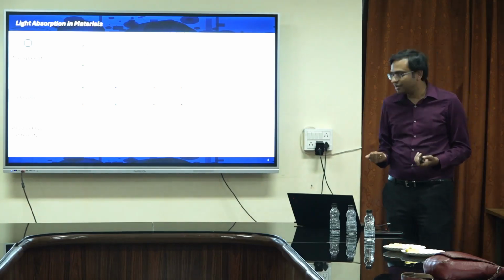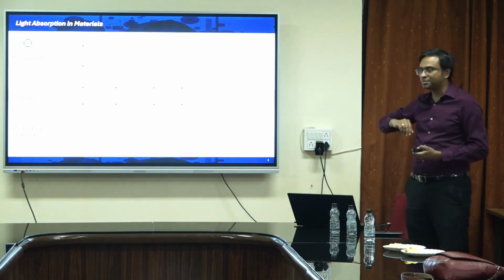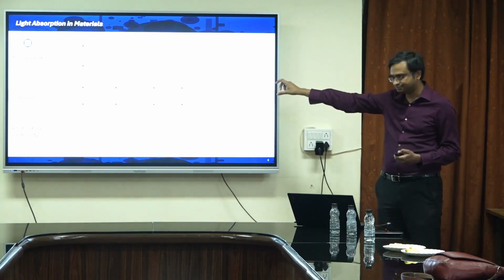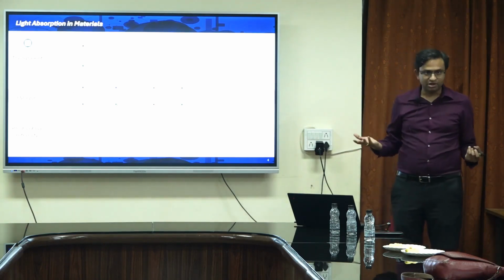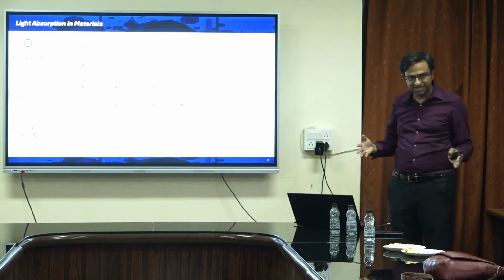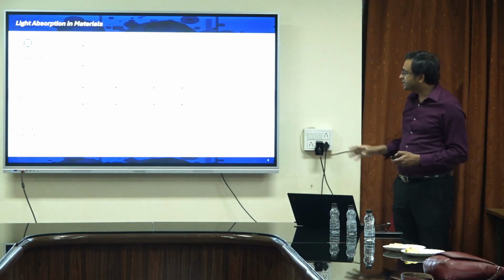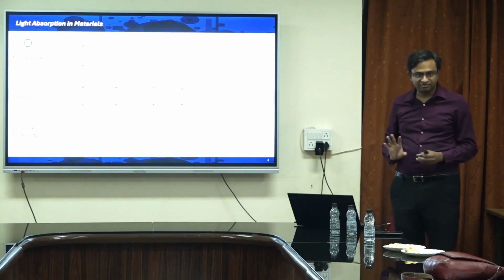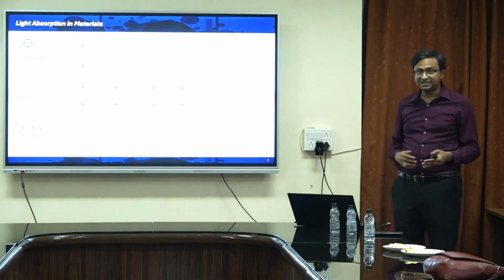A monolayer can hardly absorb light, it's very small. But the interesting part is, if you look at the absorption coefficient as a function of wavelength, of course if the light energy is more than the bandgap, then you can absorb, right. But if it is less than the bandgap, you cannot absorb, right. That's the limitation. That's why there's a cutoff wavelength for the light that you can absorb using any material. And then there is this absorption coefficient. Generally the absorption coefficients are of the order of 10 to the power 4, 10 to the power 5. This is a typical number per centimeter. That's the amount of percentage of light that you will absorb.